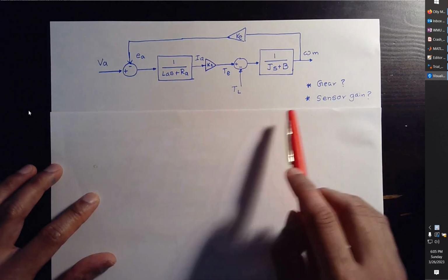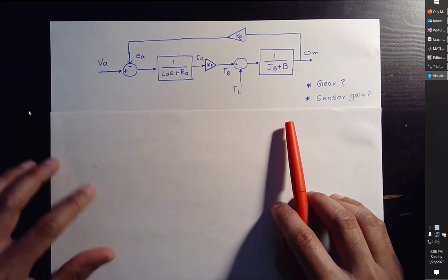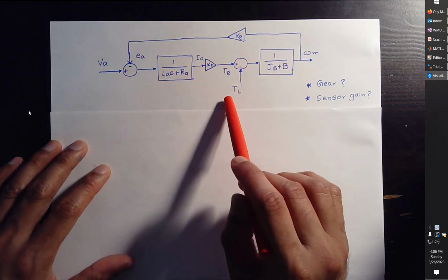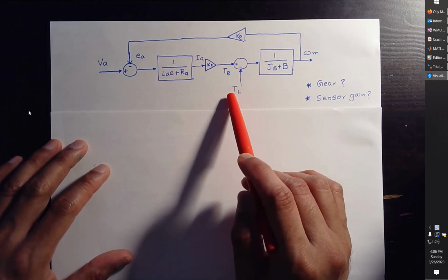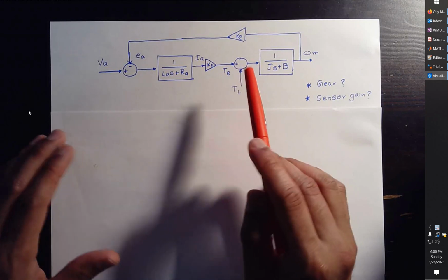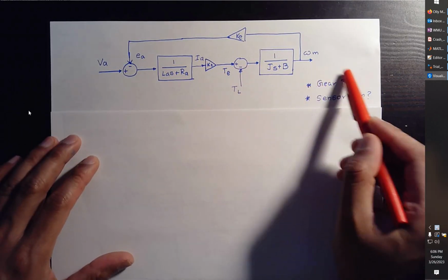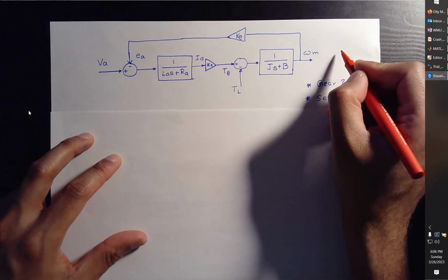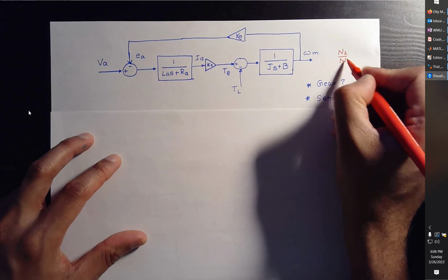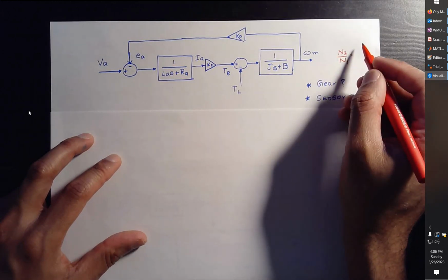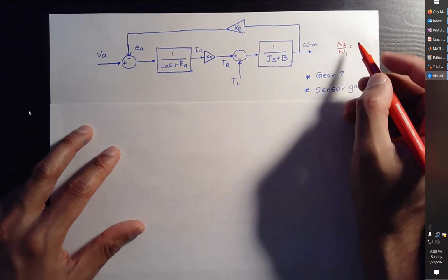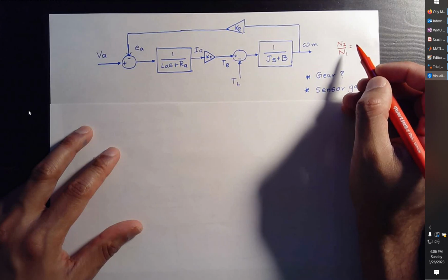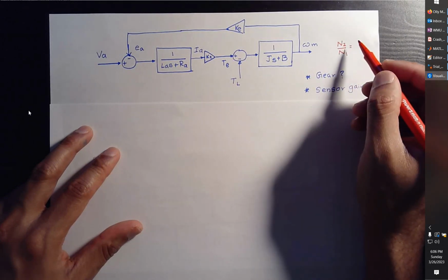So last time we left off with our open loop block diagram, right? And we said we're going to be using this model, or at least a modified version of this model of the DC motor, to implement our controller around that system, because this is our plant. Then I left the question with you to decide where the gear ratio would end up, and make sure the gear ratio that you are using is N2 over N1, as I mentioned in e-learning, because this is basically used as a torque amplifier. Torque amplifier meaning the output torque from the motor, which is the electromagnetic torque after some of the losses, needs to be amplified to drive the load that we are working with.